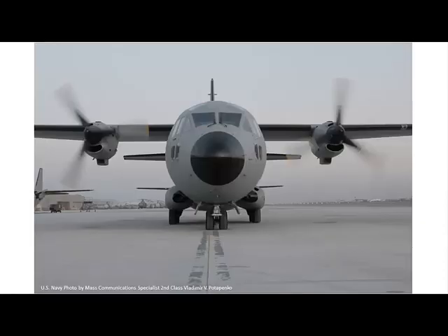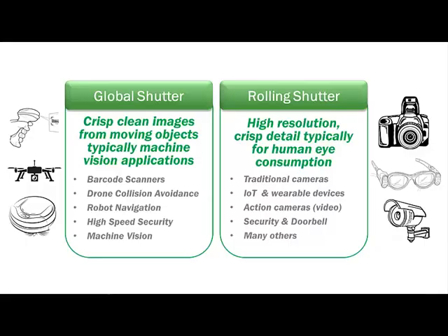An example of this is when you take a picture of a spinning propeller on a plane with a standard DSLR camera. It creates a cool artistic effect on the camera image, but it's not true to life. It makes the propeller appear bent or unnaturally twisted in some way. This is because the rolling shutter actually exposes and then reads out each row separately within the same frame, resulting in a row-to-row image skew.